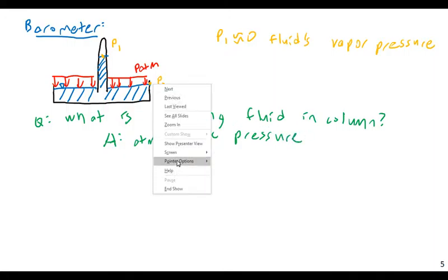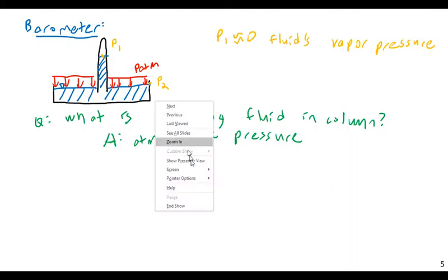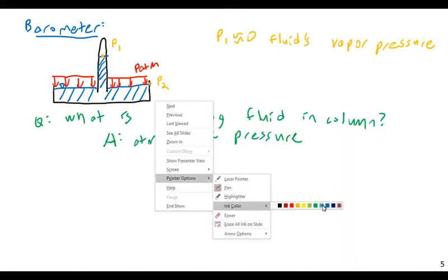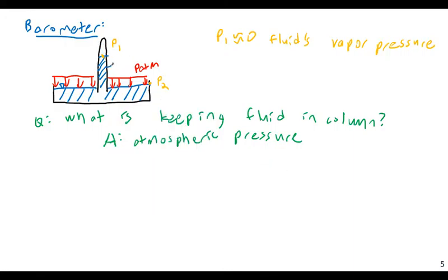And I will mention what kind of fluid we tend to use for these. Well, we don't actually use liquid barometers that much anymore, but if you were to construct one, you don't usually use water, and I'll discuss why in a bit. I would traditionally use mercury, so I would have gamma Hg for the specific weight of mercury.